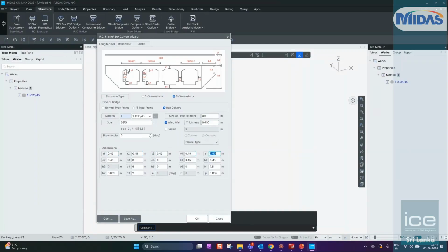so the vertical dimension of the haunch. The software will generate the haunch based on the averaging depth. Okay, it will not model an exact trapezoid here, but instead it will model equivalent thicknesses of rectangular plates.